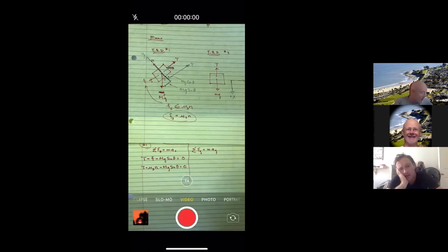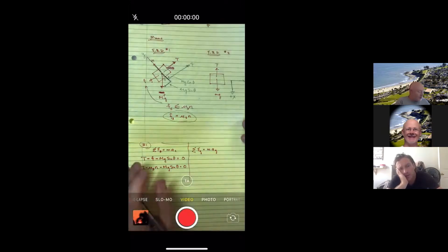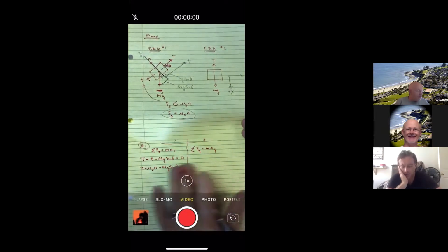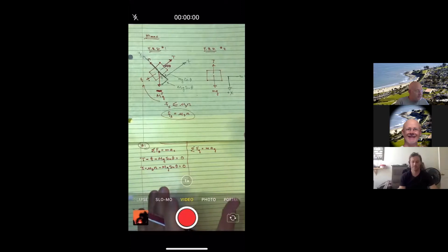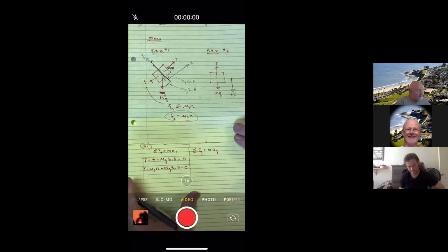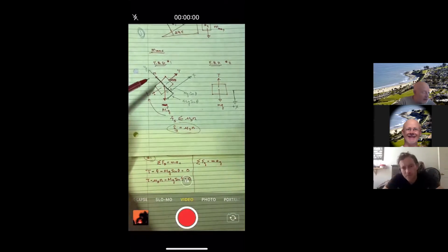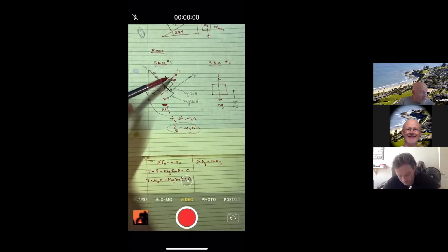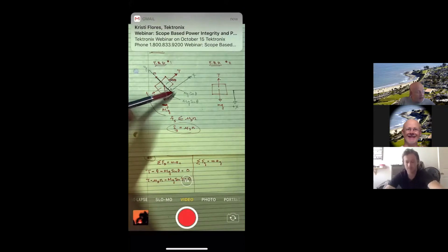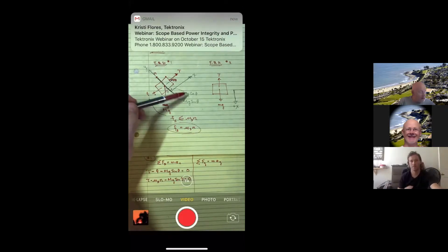Okay, good. Now, also, let's do the y direction for this box number 1. And so again, come look at this free body diagram. The normal is clearly all in the y direction. And we kind of stated earlier that the tension and the friction is only in the x direction. But the force of gravity, the mg, does have a component in the y direction. This is that mg cosine theta.